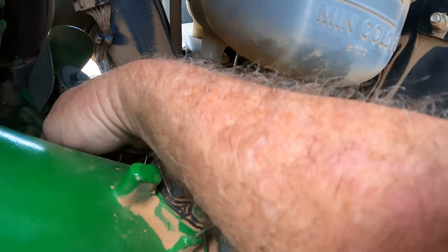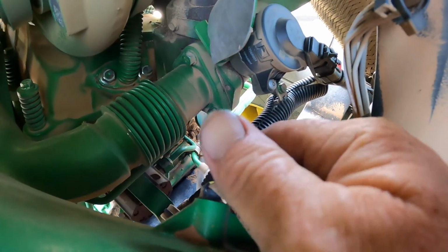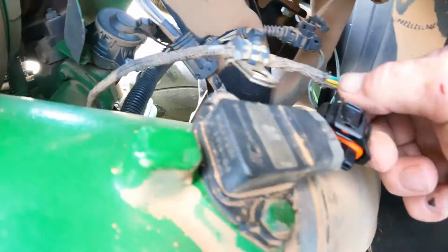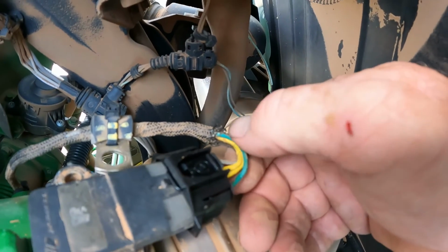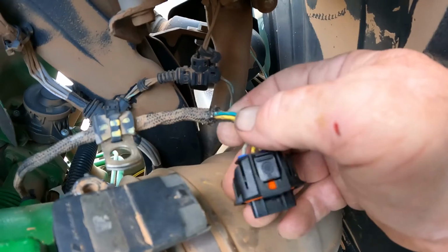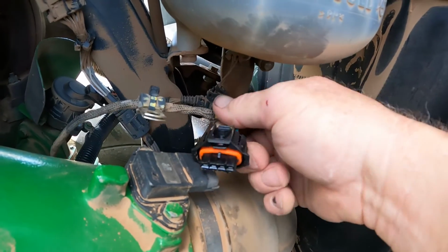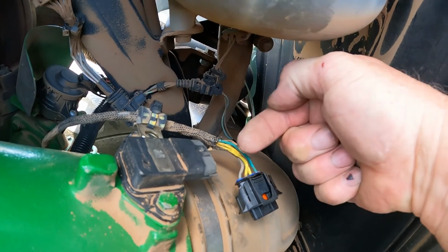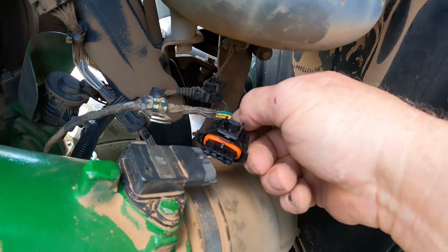And so I'm gonna get a little bit more slack down here on the bottom side where there's another connector or another wire holder, okay? To give me some more slack to be able to plug that in and not be pulling on the back side of this connector housing, okay? And so keep that in mind to try to remove and get as much slack as you can so that you're making a nice rounded area right there to go in straight into that sensor.